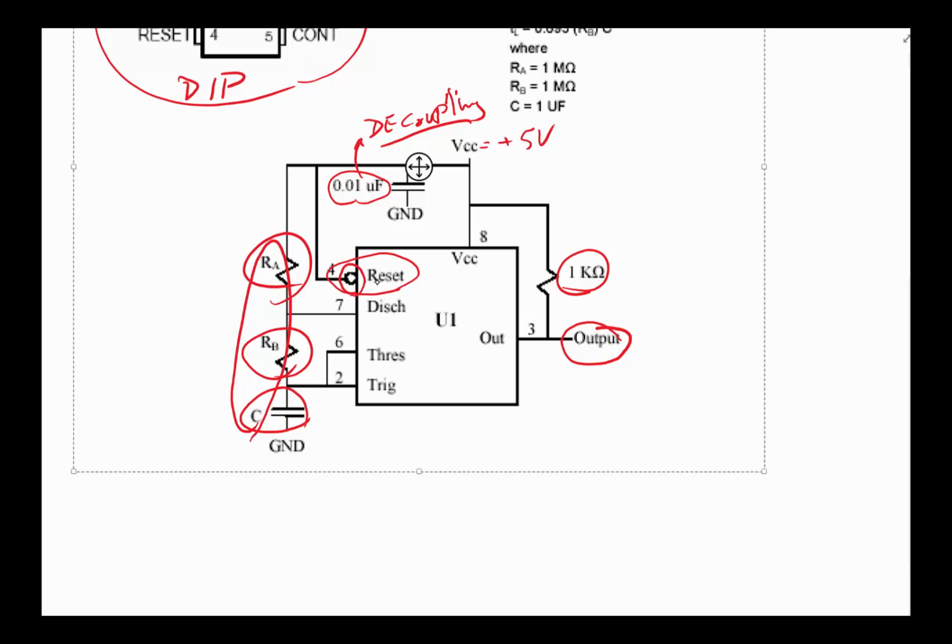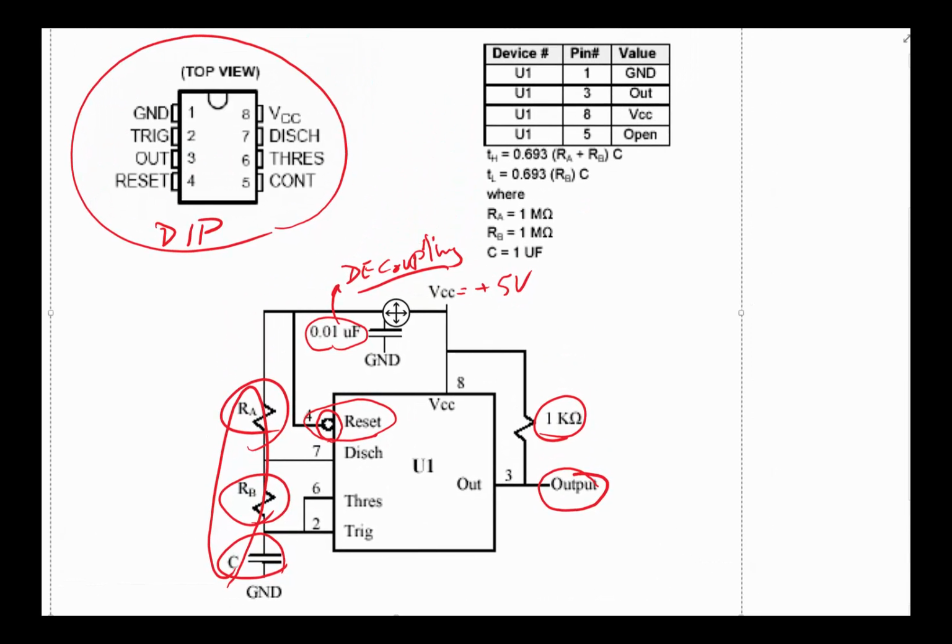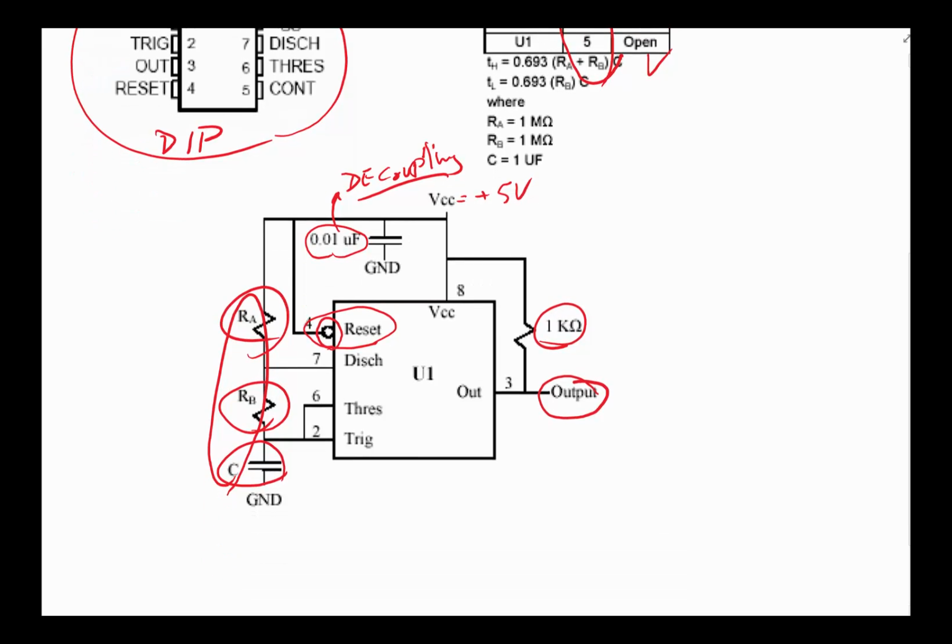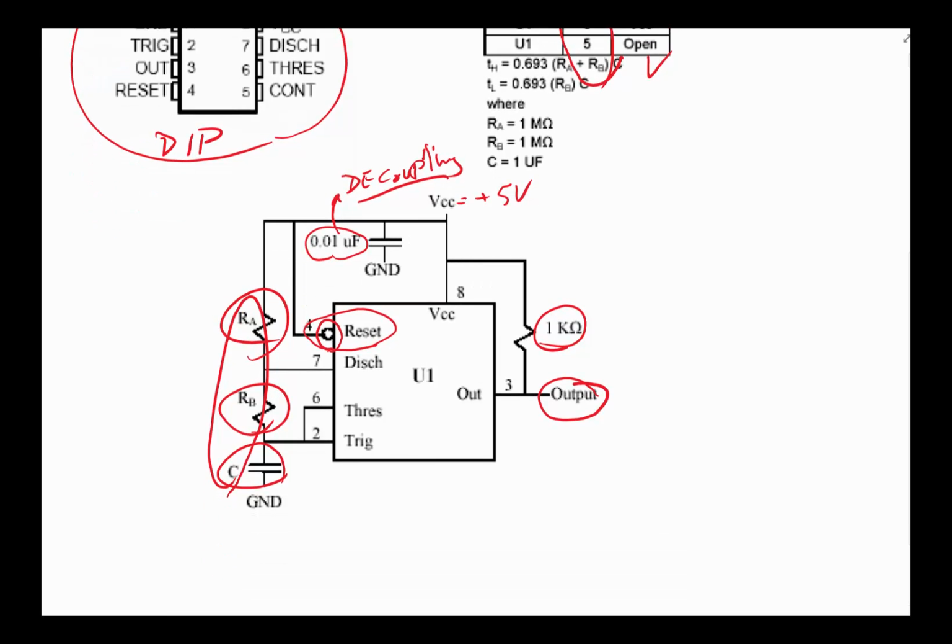When you're wiring this, one of the most common things I've seen is people forgetting to make these connections because they're outside of the schematic. Remember, we do this to simplify your schematic. The biggest one I see is ground being missed. Make sure that doesn't happen to you, and make sure you connect it so you can get a nice clock coming out of it.